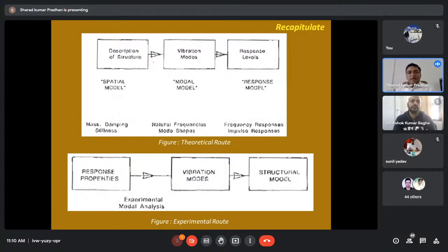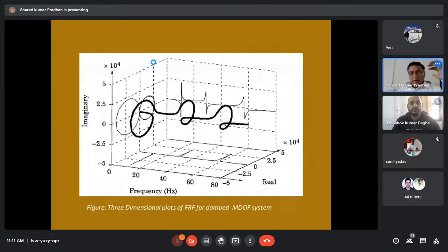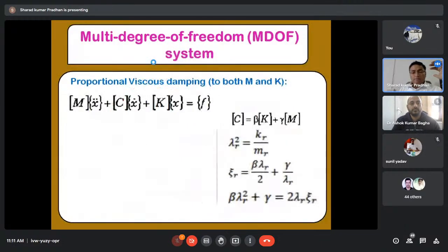Whenever you manipulate this, you will always get displacement FRF, which can be converted into velocity FRF, which can be converted into acceleration FRF. And if you take the inverse of them, you will get dynamic stiffness, apparent mass for acceleration, and a third thing I've forgotten. So three inverse quantities are going to be there.